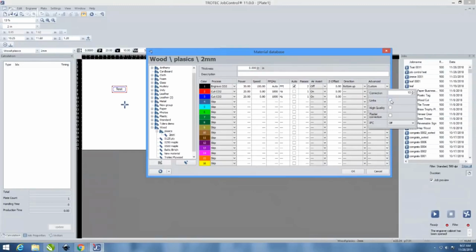This is a really important feature for certain plastics, namely the metallics. If you have this off, you'll find that if you engrave, my favorite example is the word lawyer. There's an ascender above the lowercase l or even the uppercase L, and there's a descender with the Y in the word lawyer. And you may find that the top of the L and the bottom of the Y look a little bit different in the engraving result than the rest of the word. And that's because the laser is moving only over that area. So it's engraving at a much, much slower speed than it is when it's hitting the rest of the word.